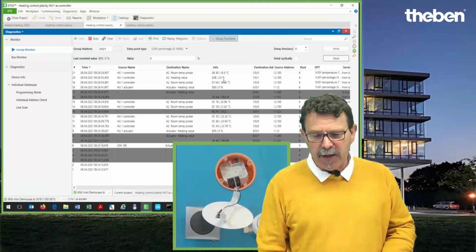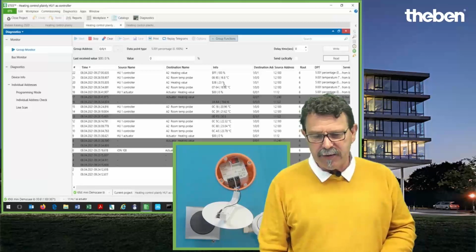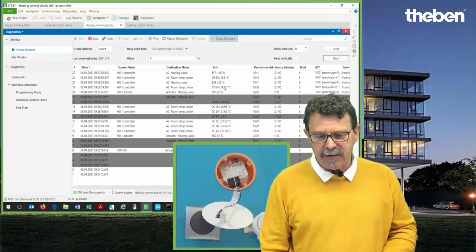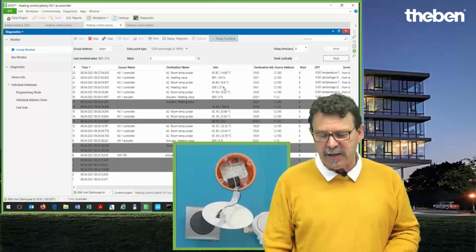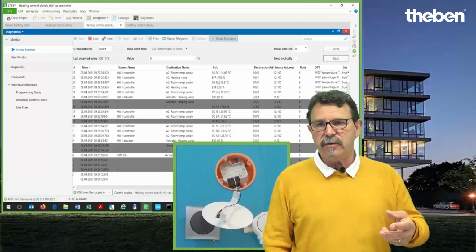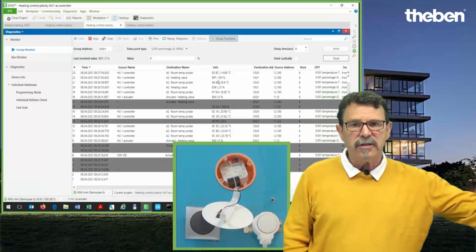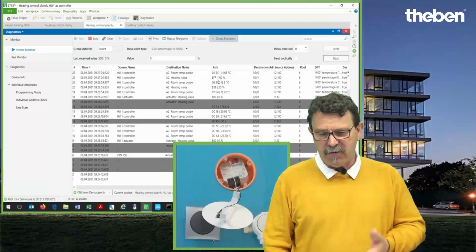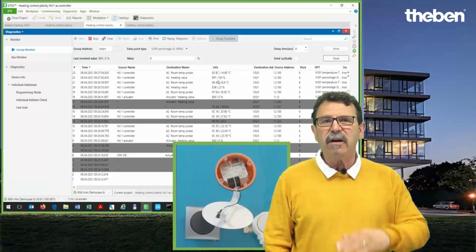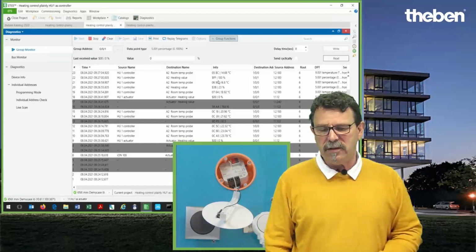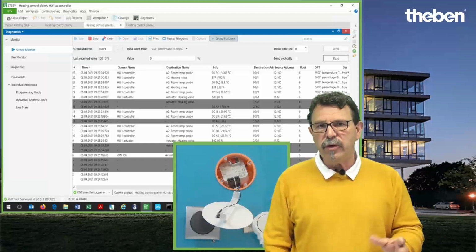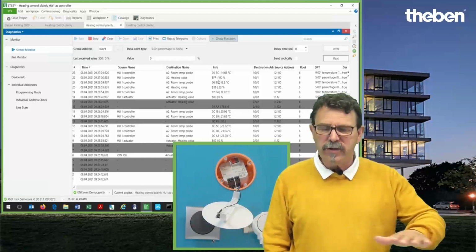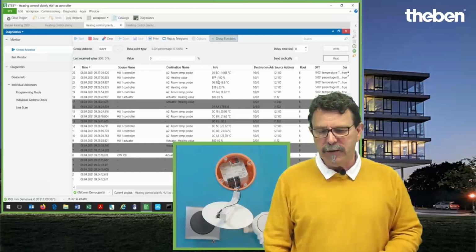So that means we are now undershooting the heating system. It is a certain slow process. But you see now the heating value turns automatically to 100%. So that means this valve is opening totally, because there is a demand: 14 degrees now is by far underneath our desired preset temperature. And due to that, we open the valve fully. The warm water is flowing through, the pipe is fully open.